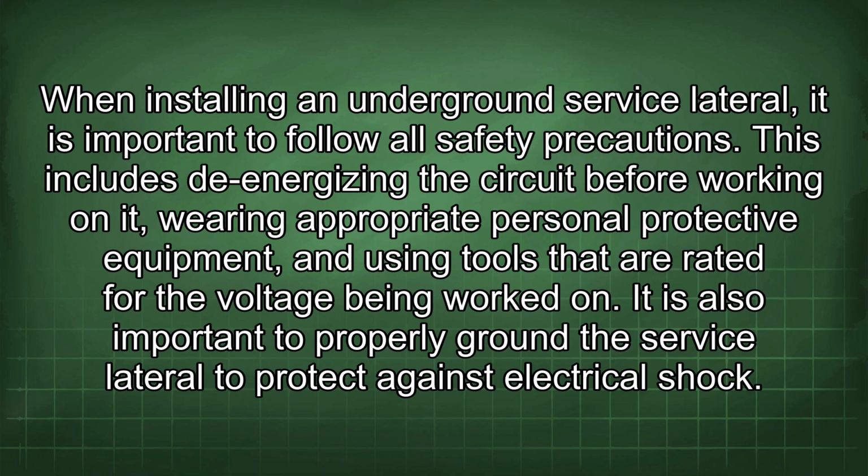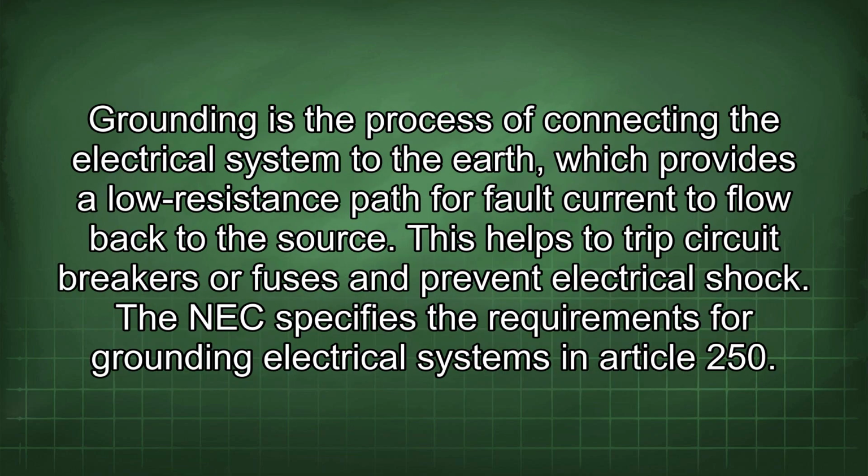It is also important to properly ground the service lateral to protect against electrical shock. Grounding is the process of connecting the electrical system to the earth, which provides a low resistance path for fault current to flow back to the source. This helps to trip circuit breakers or fuses and prevent electrical shock. The NEC specifies the requirements for grounding electrical systems in Article 250.